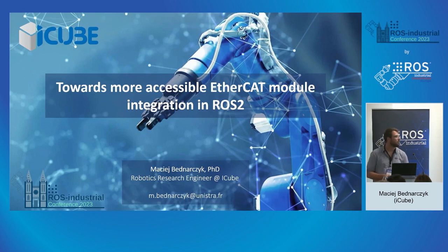In fact, currently, if you have several joints on the same module, the system that we developed is not made like this, but two possibilities are available. Either you create your system as a GPIO with the different states that are coming from the different components. Secondly, depending on what module you are using, in many EtherCAT modules you can separate different PDOs that are linked to the different joints that you would have.